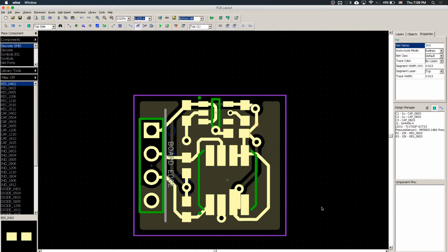So in practice, PCB layout is intuition. It's a skill of intuition. So you have to build it up by practice and by doing it a lot, through a lot of iteration as well. I usually route my board twice before I send it out to be printed, such that the first time I just experiment with all sorts of configurations, and the second time I'll have a better idea of where everything will be placed.